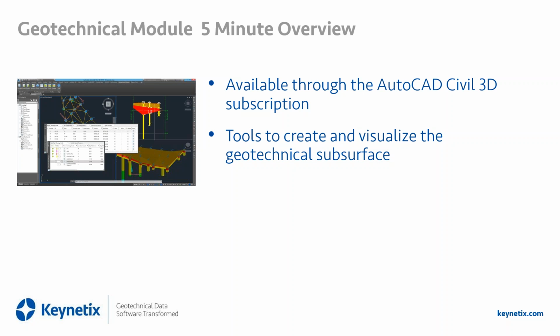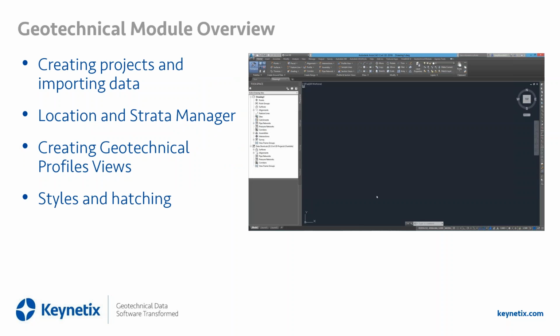It's primarily designed to allow you to create and visualize geotechnical subsurface data inside AutoCAD Civil 3D. It's as simple as that. The main elements, which I'll quickly show you in a moment, are the ability to create geotechnical projects on your local machine, import the geotechnical data, and then by using the location manager or the strata manager, visualize individual borings or boreholes. You will hear me jump from borings to boreholes. In the UK, we call them boreholes. In the US, you primarily call them borings.